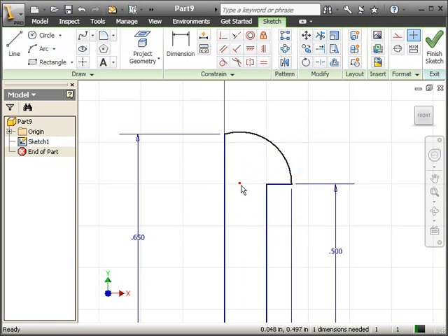This point is the center of the arc. As long as we make this point coincident with this line, our definition of this curve should be good. So coincident, the center point arc to this edge, and this curvature should now be the radius of 0.208. Let's go ahead and dimension that, and if it is, then that means we're doing okay.